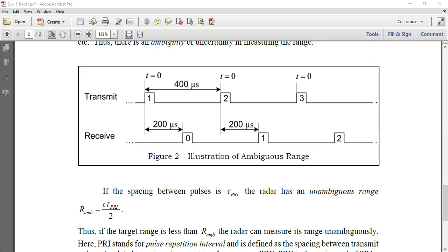Okay, so horizontally it has a narrow beam, so it keeps rotating. When you transmit in a certain direction and you get some pulse back, then you know that there's an object in this direction, then you change the direction. You keep rotating, and so you'll see the position of the objects in different directions. Over a display, you show that in this direction you have objects, using some dots, you can show the positions.